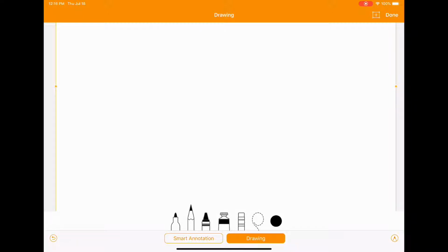So the order I like to check things in, I like to check to see if it's open, then check to see if it's enclosed, then check to see if it's partially enclosed, and then partially open. So these are the 4 different enclosure classifications that your building can be.